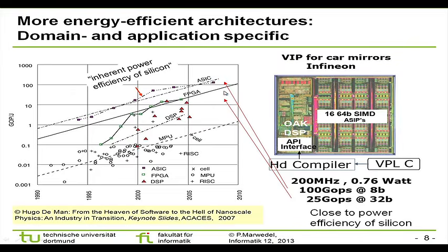This 0 and 1 that I have put in as a single bit is a sort of predicated thing. We will soon see in ARM how we can compress the instructions in a much better way. And the last instruction, can it have the last bit as 1? 1 means the next instruction should be executed in parallel. For the last instruction there is no next instruction, therefore that 1 will not mean anything.